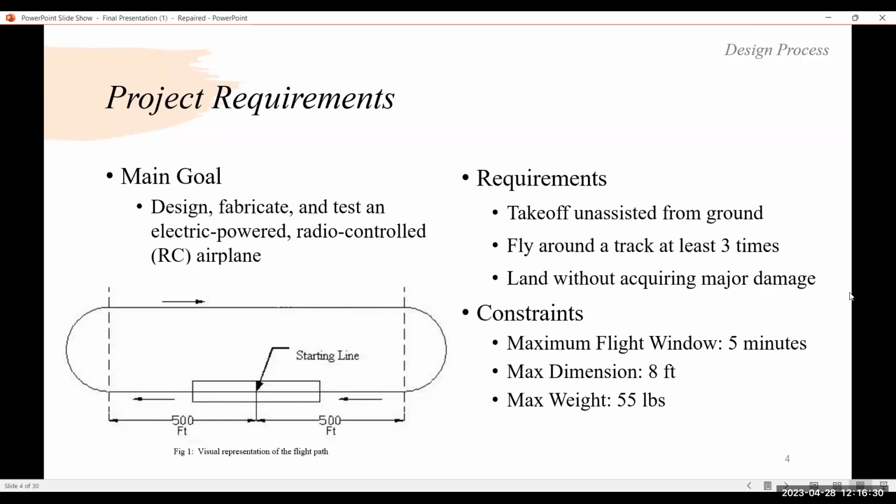Okay. How much did the plane weigh in the end? Do you want all of the iterations, or just the last plane? The final plane was approximately 6 pounds, I believe. It was about 0.8 pounds for the fuselage, a pound for airfoils, about 2 pounds of avionics, battery, motor mounting and all of the associated servos and push rods, and then another half pound approximately for landing gear. Okay. And can I see the picture of the final plane design?